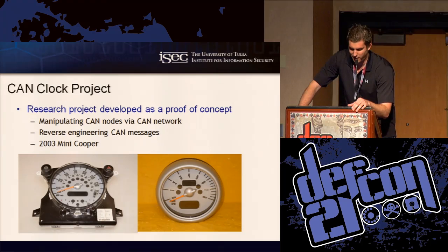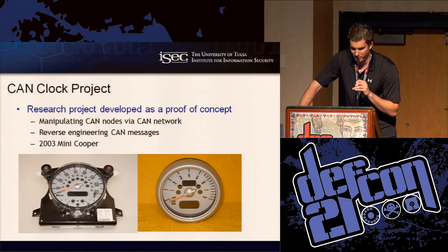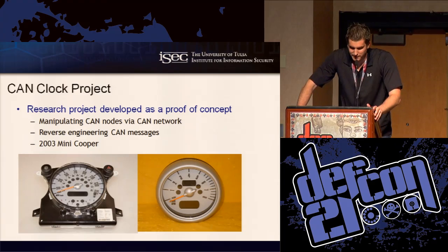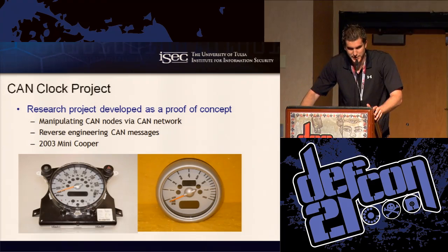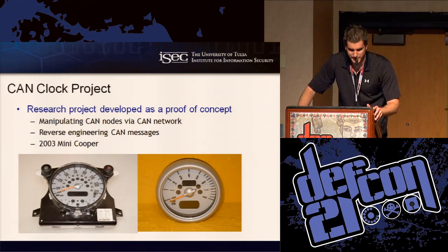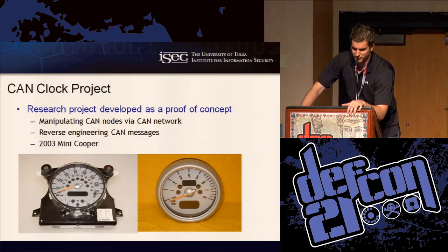There were literally two problems. I had no prior knowledge of how these systems work beforehand, so I had to build a CAN bus from scratch. And then also, with passenger automobiles, the actual message IDs that are responsible for controlling the various devices and functionality of the systems on the vehicle are proprietary in nature. Some reverse engineering methods were used to identify the message IDs themselves.